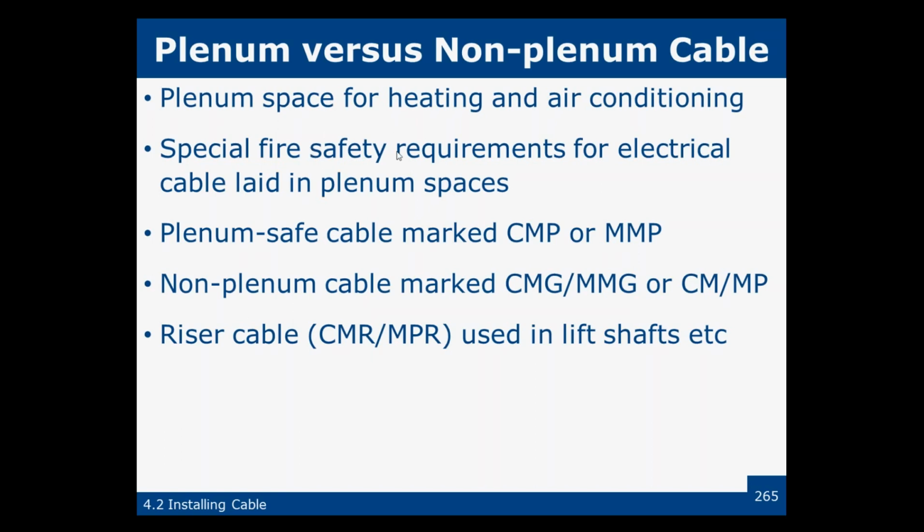The reason we need plenum cable is that it's fire retardant and supposed to be self-extinguishing. It also is not as smoky, and it doesn't have as many toxic gases.